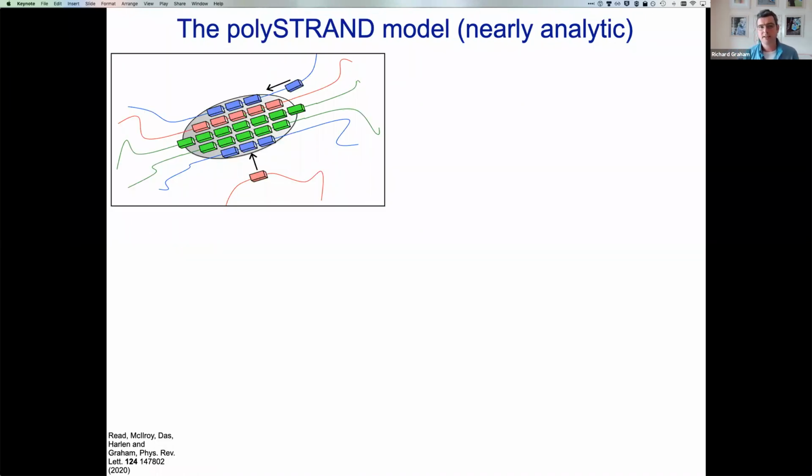Okay, so this is how we calculated the nucleation barrier. Now, bear in mind, this is for a large number of different species, all with different degrees of stretch, so different attachment rates, and we want to write down a model that's consistent with the kinetic Monte Carlo algorithm that I set up. So we've got many different species with different values of this order parameter and different concentrations in the melt, all trying to attach to the nucleus. And so we want to write down a free energy of a nucleus of this size.